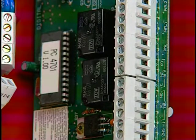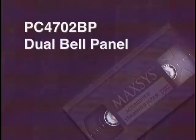Also, there are 2 Form C relays on the module, one for fire trouble and the other for fire alarm. These relays are not programmable and can be used to interface with other equipment, for example, to release access control doors in the event of a fire.